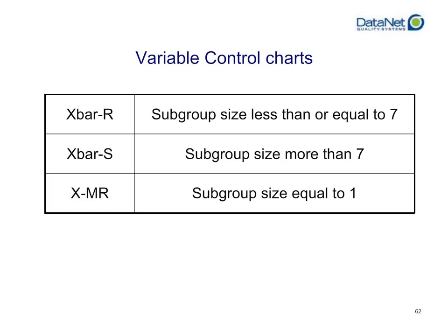However, your mileage may vary based on what you're trying to do with your process. You're plotting your X bar, that's the average of your subgroup, and the R, which is your range, your largest minus your smallest value within your subgroup. You plot it on a combo chart, a top chart and a bottom chart.